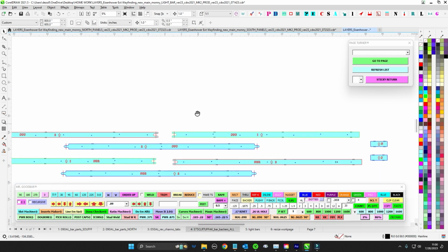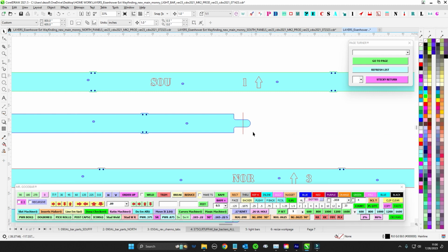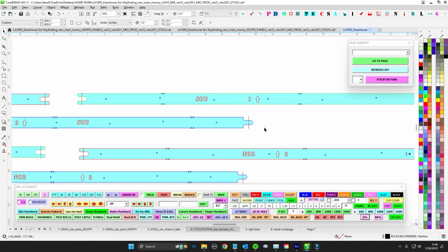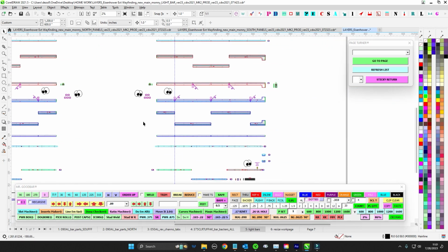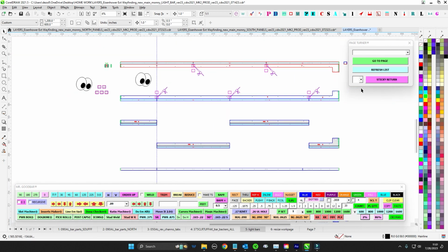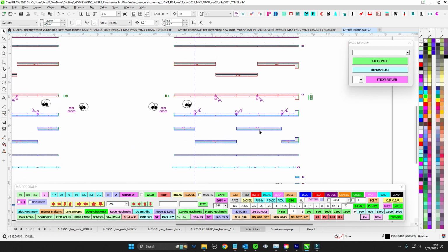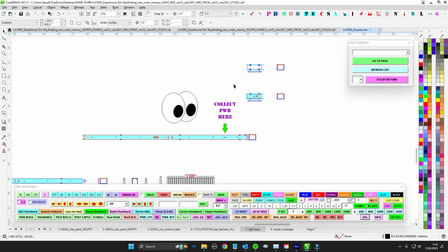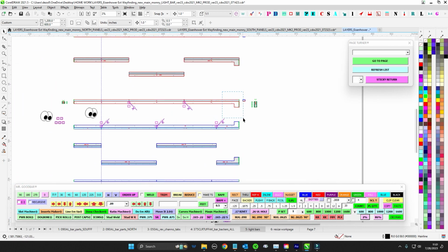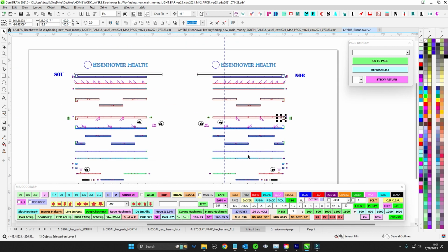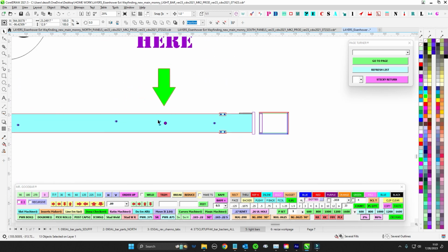And then I have 3/8 Macrolon. Again, this looks very similar. These joints open and close with the heat, so that way we have a little bit of room there, and hopefully it's not too much buckling. So you're just going to laminate those seam pieces. Once all this is together, laminate the seam pieces, then you should have one contiguous piece. The other thing, you collect the power towards this side over here where the little bendy notch is. That will be where power collects on both of those. So just look out for that little power hole there.